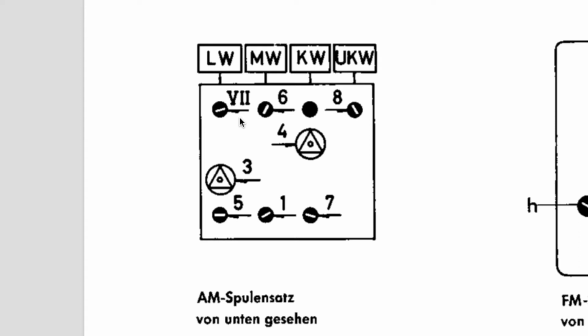Now, how are we going to do this? Well, we're going to set it up assuming this is correct, and then we're going to make very small adjustments where we're supposed to, and we listen out to see whether that makes a difference. If that doesn't make a difference, then we know we might have a problem. We may have to find the corresponding coils and capacitors by looking at the circuit all over again. But I think that might not be necessary. We'll just play it by ear and see. So the next stage is set up the radio and set up all the equipment and get ready for this part of the alignment.